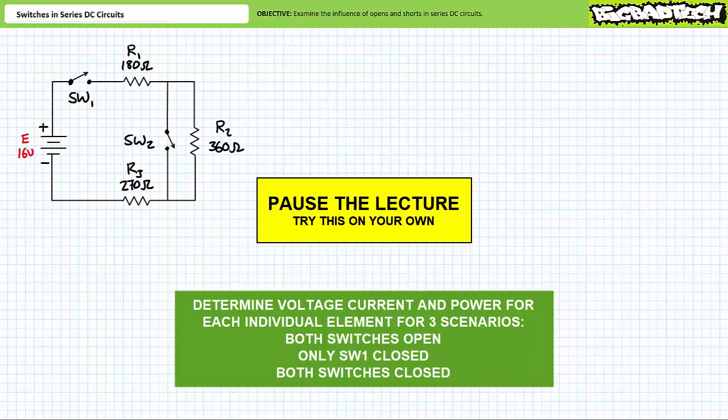If switch 1 is closed and switch 2 is open, this would create a series combination of all 3 elements. However, if both switches are closed, this would create a series combination of only R1 and R3. R2 would be bypassed by the switch and effectively removed from consideration. If you're tracking, you should have obtained the following results.